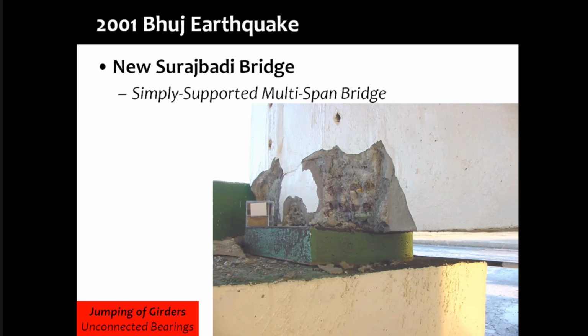So the catch is simple. A large number of people in India have said none of our bridges got damaged. Yes, the answer is very simple, because we never connected our bearings. And we got lucky that most of the bridges were not shaken. Once our bridges get shaken and they start dislodging, you will see that this is not an acceptable solution.